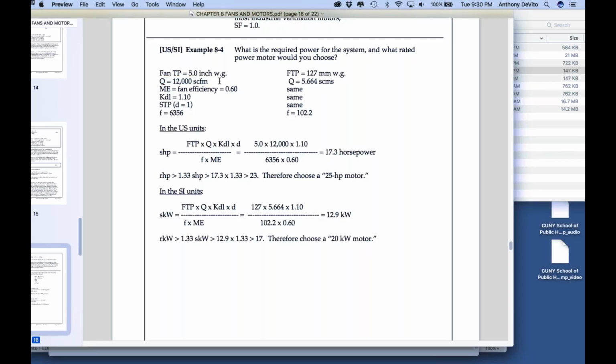The outlet, you started with 0, right? I mean, the fan is just discharging open air with no ductwork on it. The static pressure is 0 on the outlet, right? But normally you can't do that. You need to get the exhaust out of the building, right? If it's on the roof, maybe you could do that. But if it weren't, then it'd be 0, right?